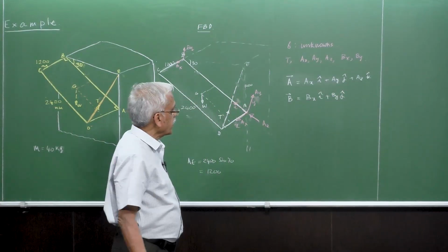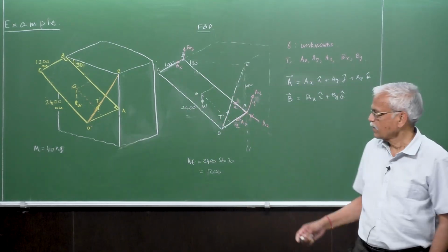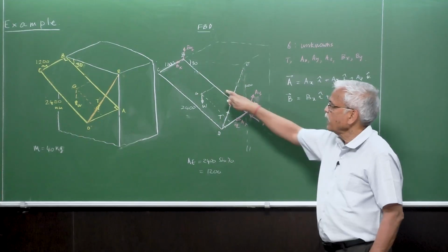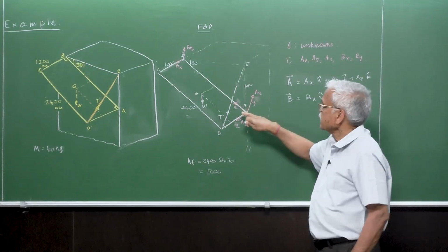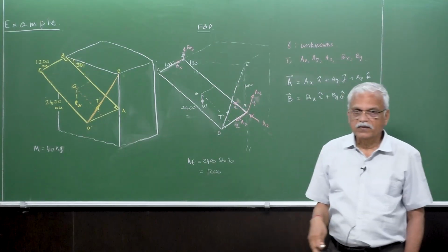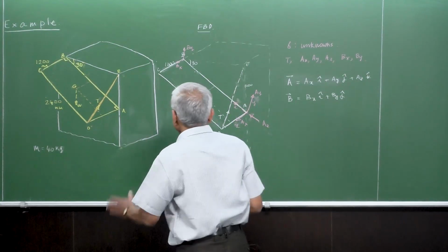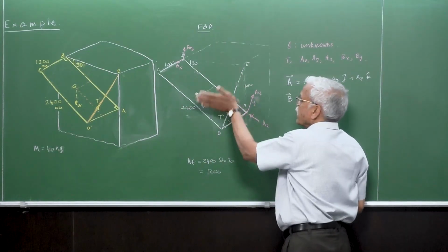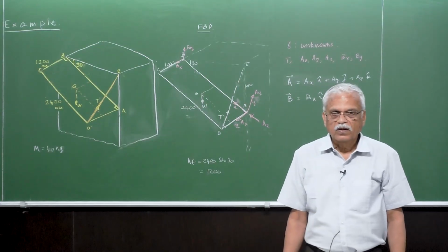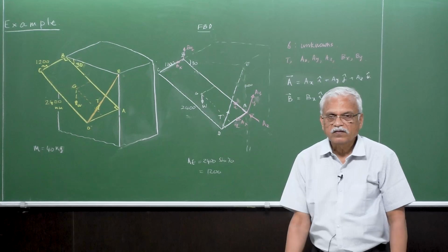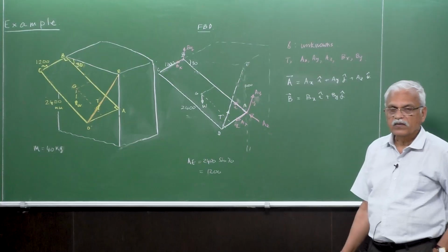Another important thing is that this XYZ is also very convenient, particularly this axis Z. We would like to have one axis along this line AB about which the door can swivel. So why we require it? When the door can swivel about this AB, when you're going to solve these equations, the moment about the AB, the Z axis, needs to be 0.